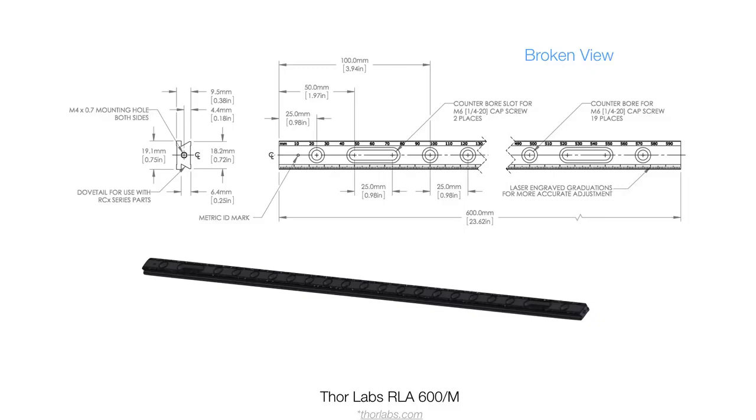The important thing here is to just make it obvious where the break lines are and not make the break lines confused for object lines. So you can use jagged lines, you can use curvy, free-handed lines, as long as it's clear that it's not real geometry. Those are all the alternative view methods I have for you.